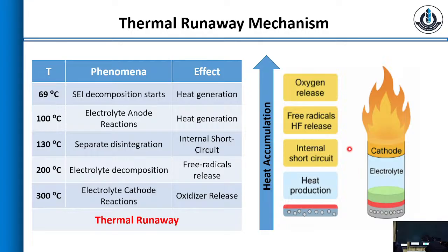And then it will basically release oxygen. Now you have oxygen as well as these free radicals hanging around at 300, 400 degrees Celsius. So that now leads to a fire. Okay, so that will start the vigorous combustion process. So this is the process in which your thermal runaway failure typically happens.